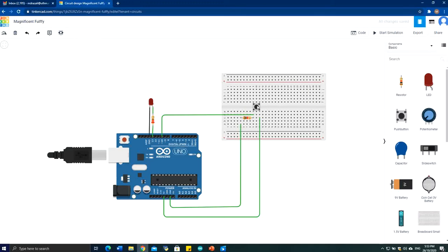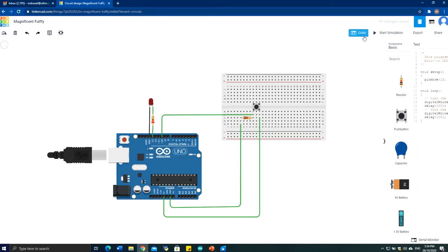Once you press this button, the 5 volt will be connected to this circuit. Since you have some resistor here, the Arduino will read the input as 5 volt. So for this particular case, once you press this, pin 10 will be triggered high. So the condition can be used to control the LED. Okay, so we are settled in terms of our hardware arrangement. So let's go to the coding part.